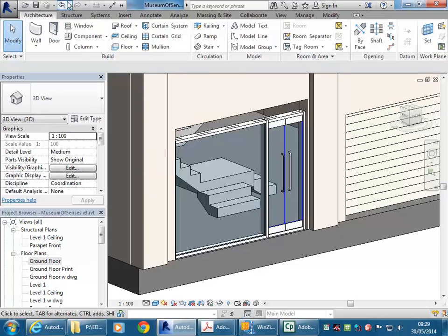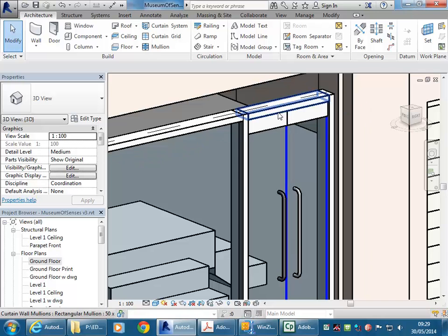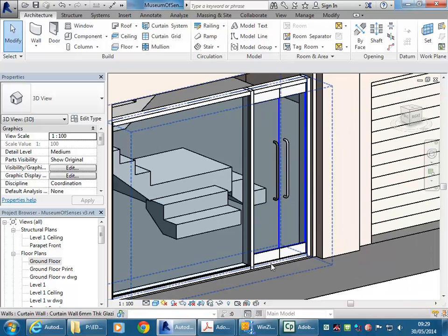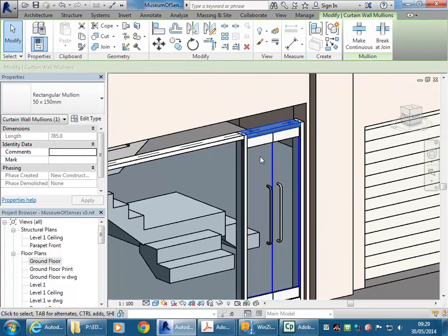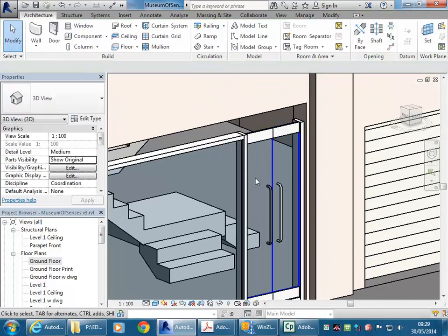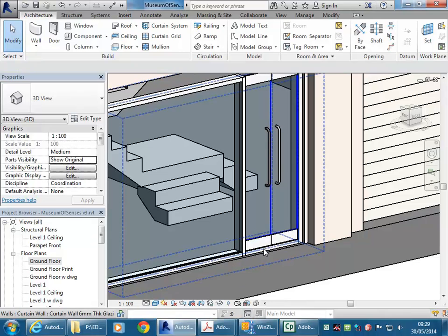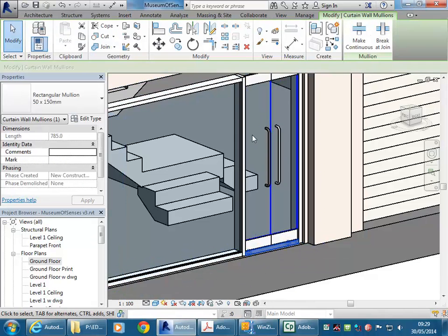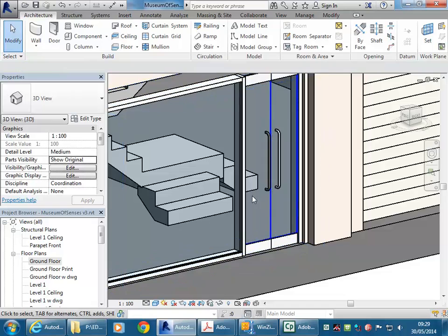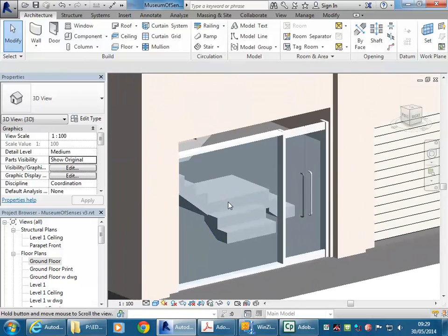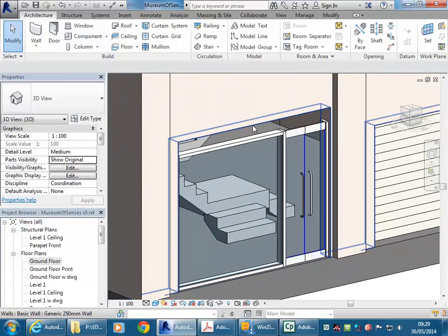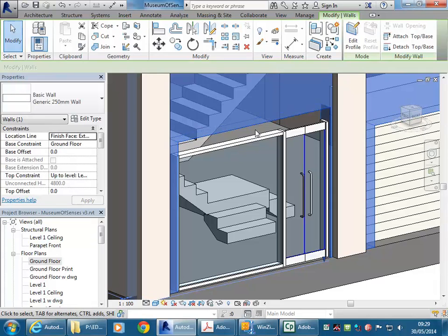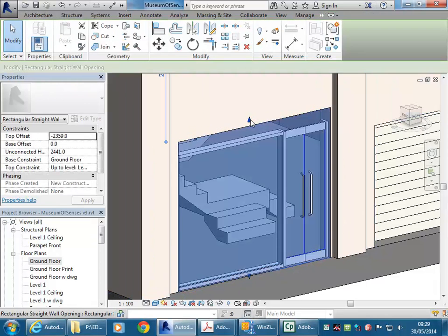But, now, I just better change something there. I've got mullions then going into my section where the door is. So you can always just delete that part of it. So then the one down here as well. Just make sure I get that. Delete it. There we go. So then I can bring the opening down so that it joins.